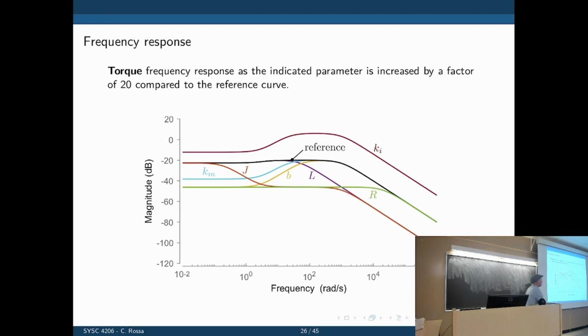Okay. So, with this information, if you were to implement torque control in a DC motor, how would you go about doing it? Choose a motor with low inertia, low friction, high Ki. Yeah, but in terms of control itself, how would you implement a controller to control that motor you chose? Sorry, say that again. I can't hear you. Control the current. So you control the current.